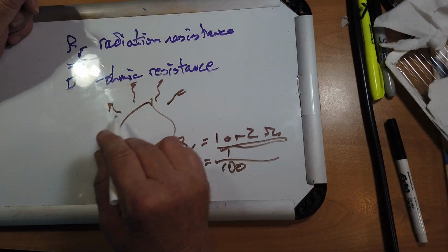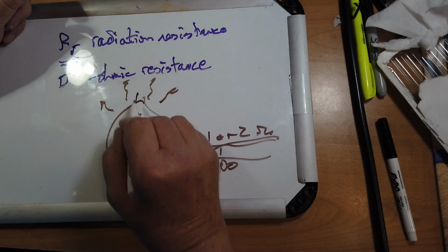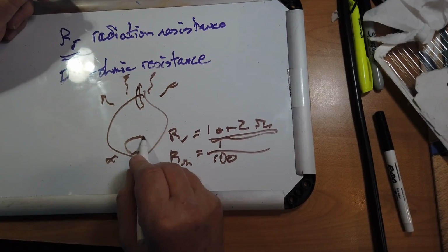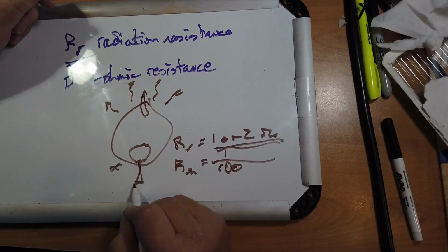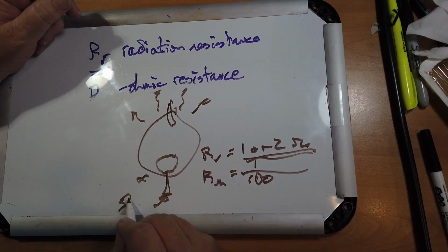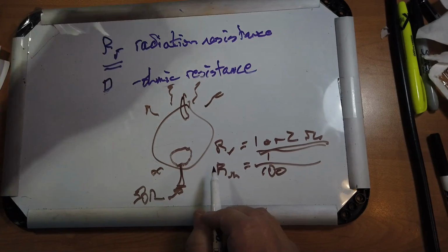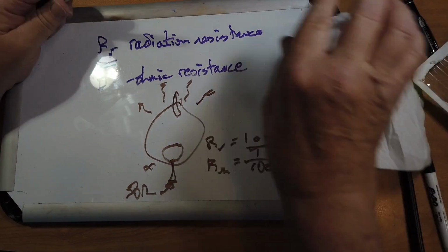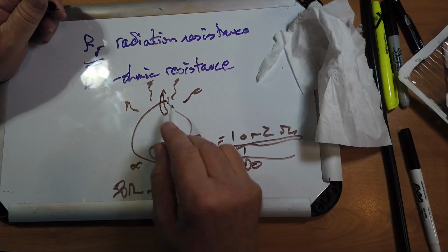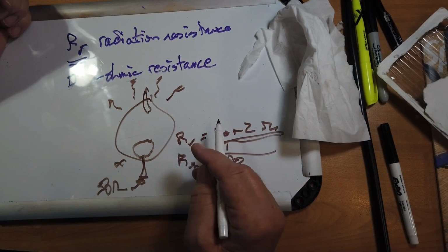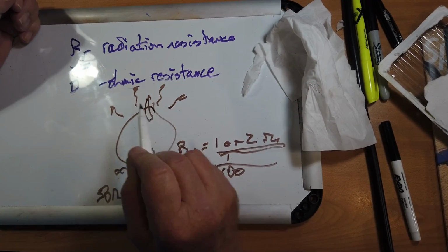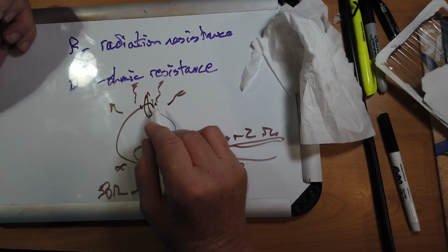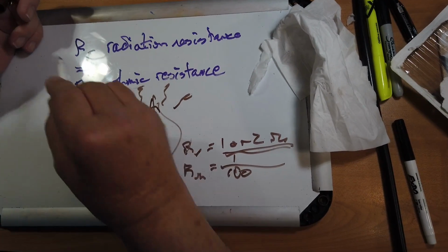Now the actual tuning to resonance is done with the big capacitor that's in there, and then you have this coupling loop right here, which is actually connected to the transmitter line. So this sees 50 ohms when this is tuned properly. So the net of this is you have to get this thing tuned so that you get very high circulating currents in it. You can get thousands of volts across that capacitor, very heavy circulating currents, in order for the thing to work properly.